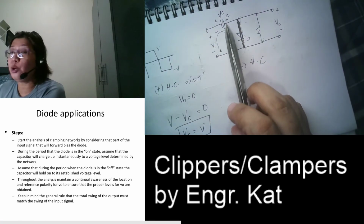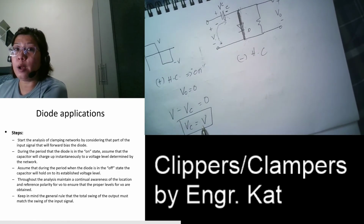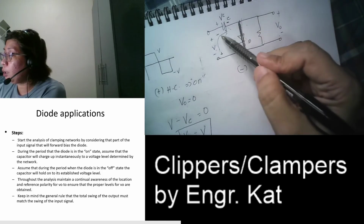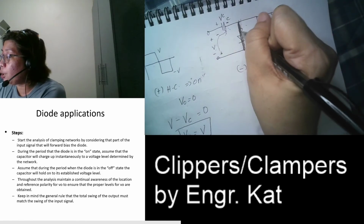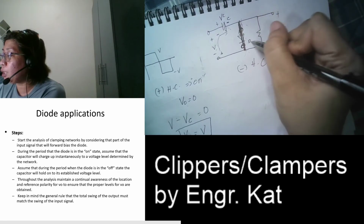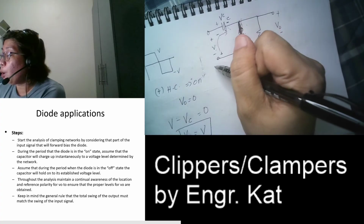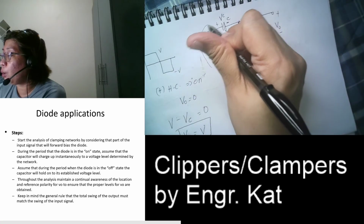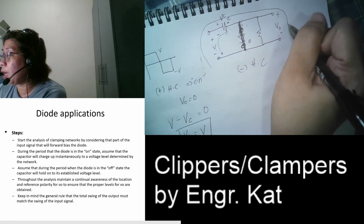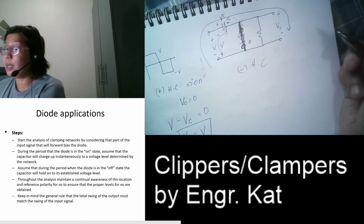So your capacitor will hold on to its original charge, which is equivalent to V. Since this is already reverse bias, your diode here is open, so this is no longer equal to 0. Where will your voltage charge go? You will be having a loop outside. And this time we have here minus and plus V.